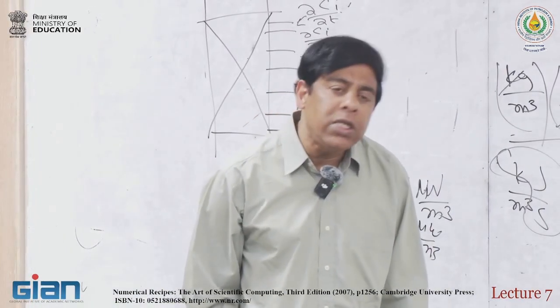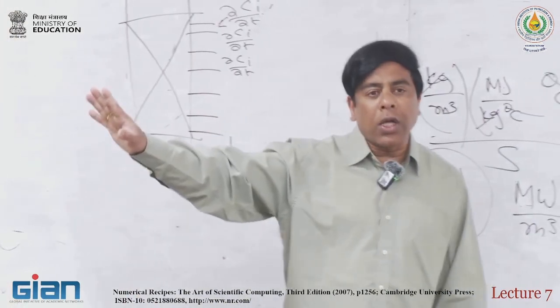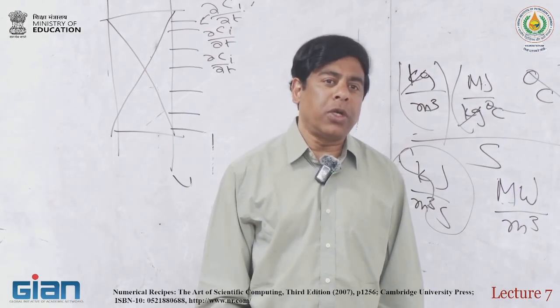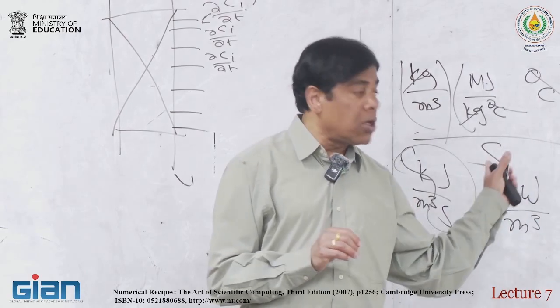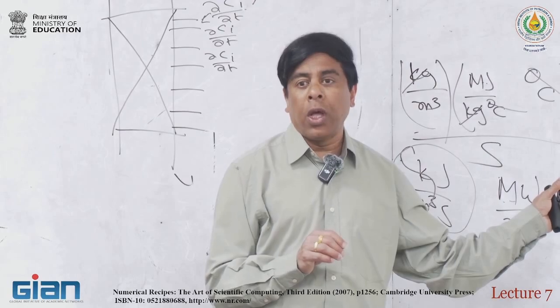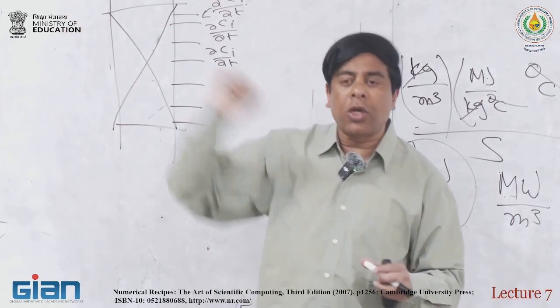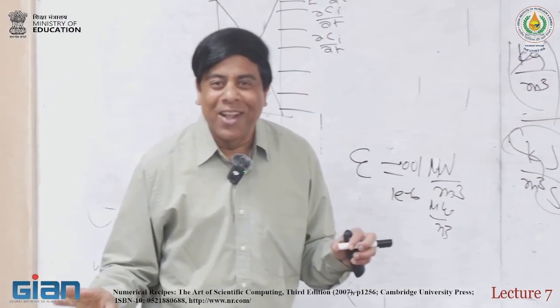Aspen internally, if you see Aspen Plus, they actually use gigajoule for many of those things, and it keeps a very high tolerance there, because many times these terms are notoriously difficult to solve. The other thing everybody has to be very careful about, and I'll discuss some of this later on, is the pressure unit. This is the one that kills everybody.